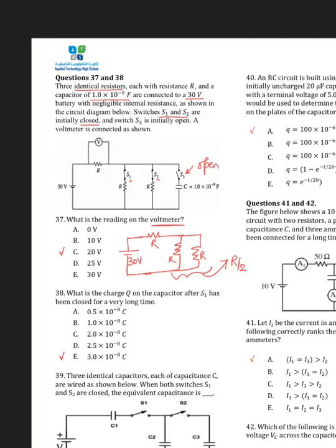So definitely the ratio of the voltage would be according to the resistors. So you will get 20 volt for this resistance, and 10 volt will be given to this parallel set of resistors, because their resistance is R over 2, half the resistance of the one which is connected directly to or near the battery.